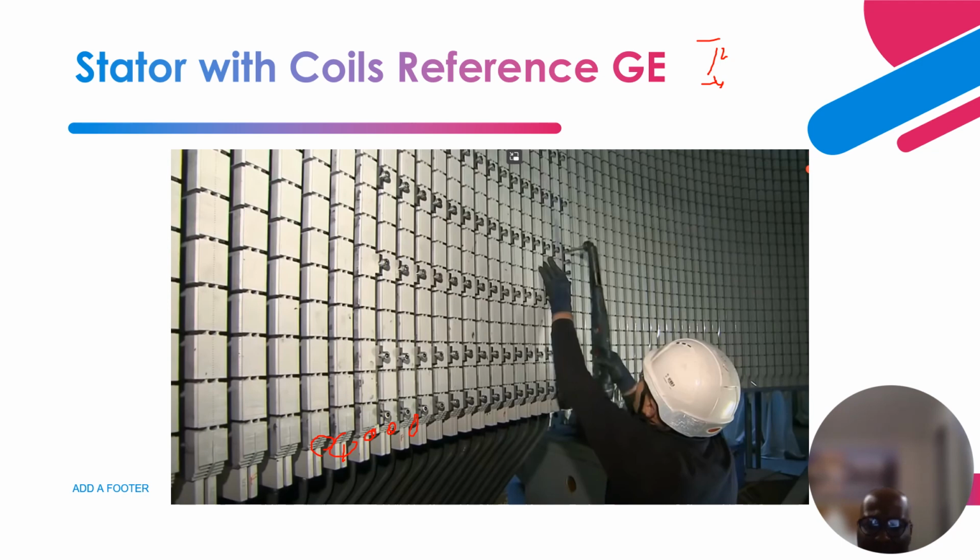The force is proportional to I squared, the fault current squared, times the area where the fault is located. That is why a lot of mechanical bracing is put into place, so that the generator can withstand all these electrodynamic forces during operation due to high fault currents.